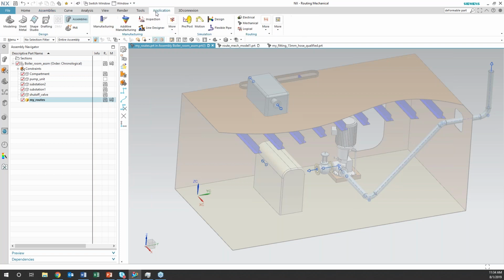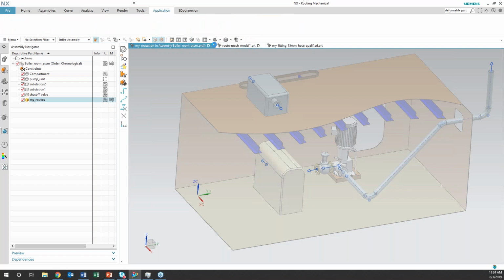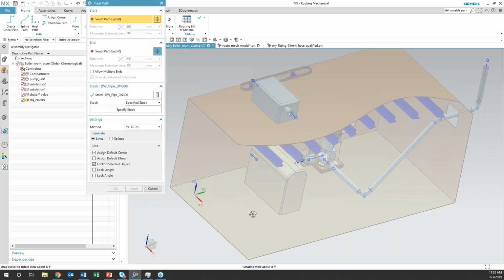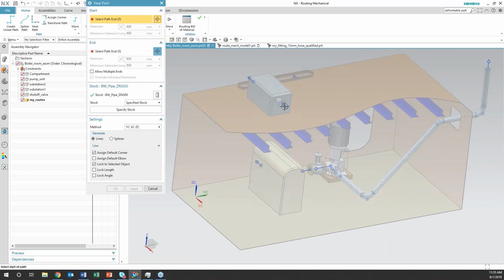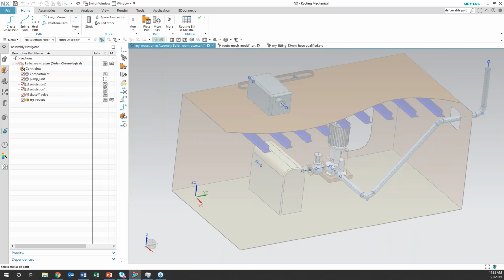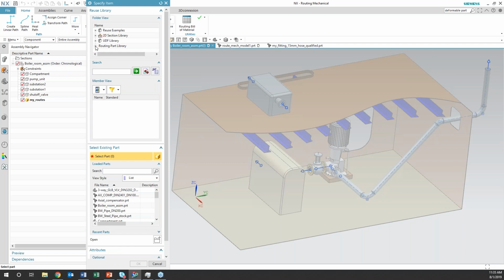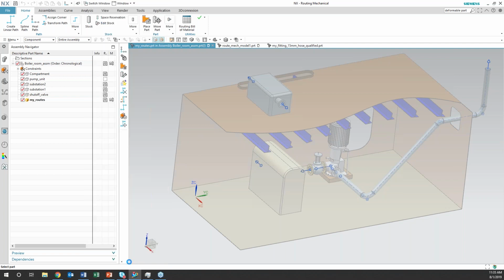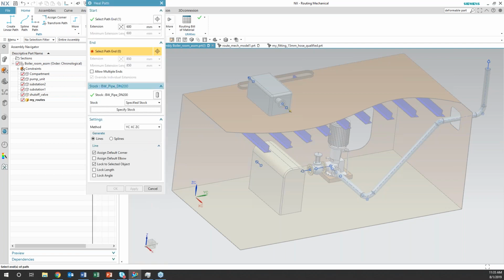Over here, I'm going to show you the heel. Back to mechanical. So, heel. As I said, heel is the coolest. You could just select the 200. Here we're on 200. Let me go back and get my 200 NPS pipes. And I know my default corner is 350. I'm going to do this with lines.